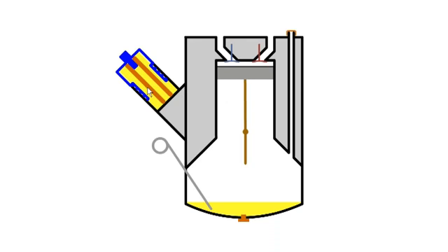When the engine is started, it will fill the filter with oil. Check the oil level and again, be careful not to overfill.